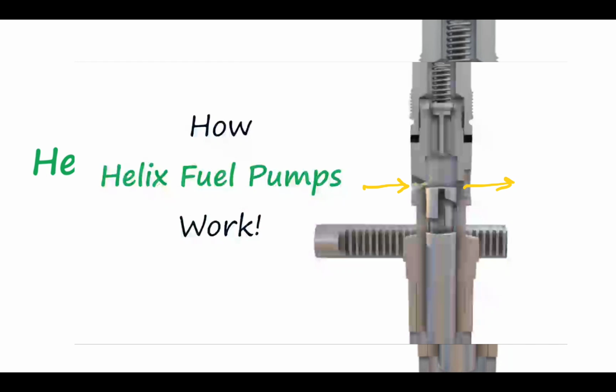Because you remember in the previous video, there was a passage here, the green one. So fuel is here and here at the low pressure, 5 bars. So we could rely on this port only. When the plunger moves down and opens this port, fuel will enter the plunger as a barrel. And when the extra fuel returns, it will return back from this port again to the casing of the inline pump. But let's watch again.